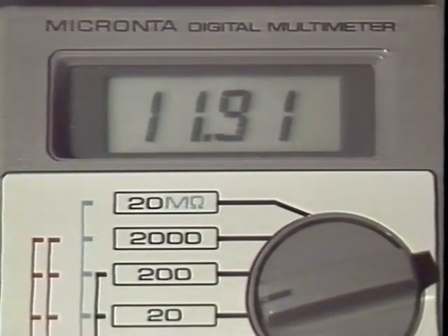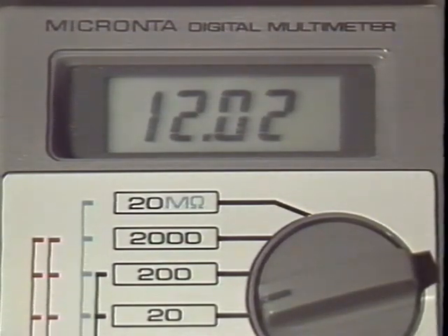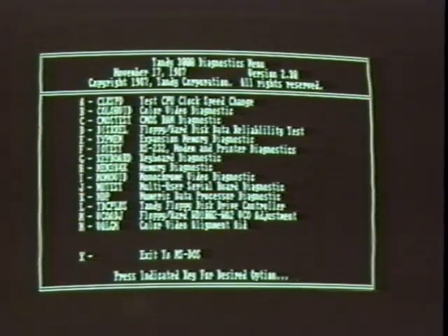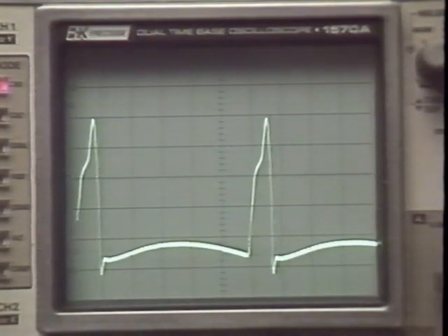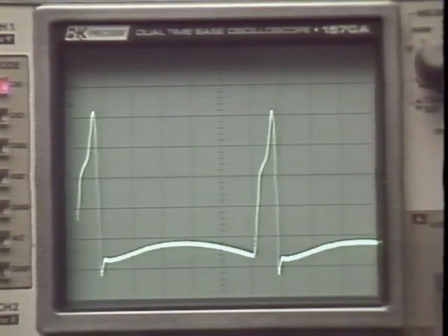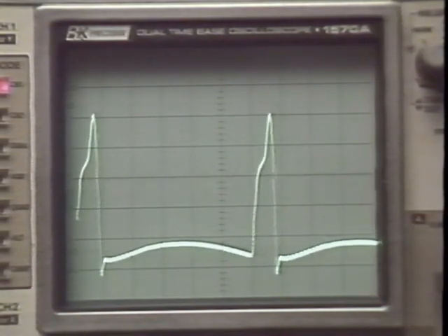The power supplies in many standalone monitors produce an adjustable output voltage. Always make this adjustment first, since the power applied to the various sections of the circuit affects their alignment. Next, align the horizontal sweep circuit, since power to the CRT itself is usually derived from the horizontal output. There are three possible adjustments to this circuit: sync, size, and linearity. Perform the sync adjustment first. It sets the frequency of the oscillator for a stable display.